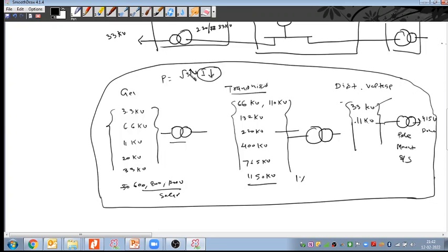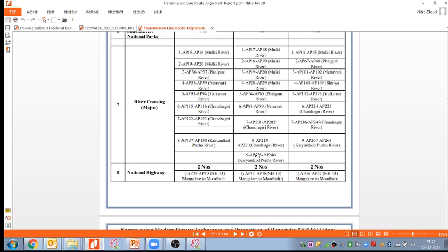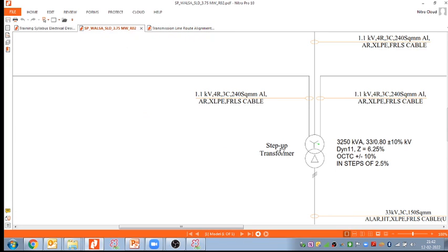Sir, I have one doubt. Yes, Rohit. Sir, from the generating station, if we are generating 33 kV, how is it transmitted? How is it stepped up from 33 kV to 132 kV? With the help of the power transformer, Rohit. You can see in this drawing also. We are using this step up transformer right now. This will step up to 132 kilovolts or 220 kilovolts with the help of the step up transformer, and that transformer we place in the generating switchyard.